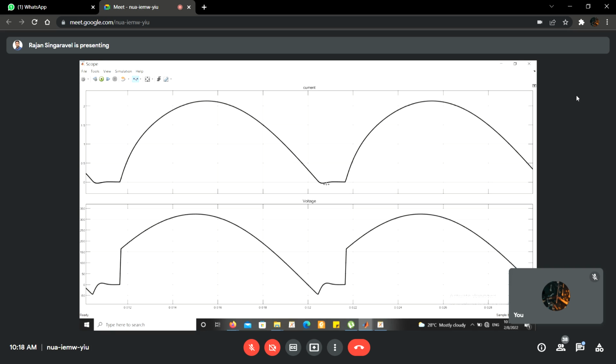The reason is, before the current becomes zero, the next set of thyristors will be triggered, so the current will start to rise in the next half cycle. So the current will never become zero when alpha is less than load angle phi.